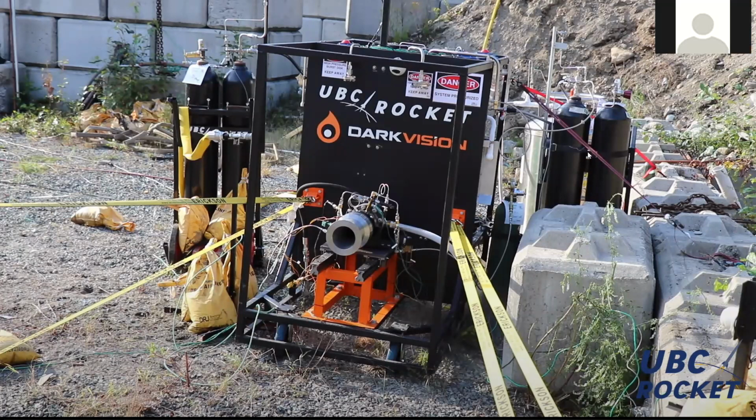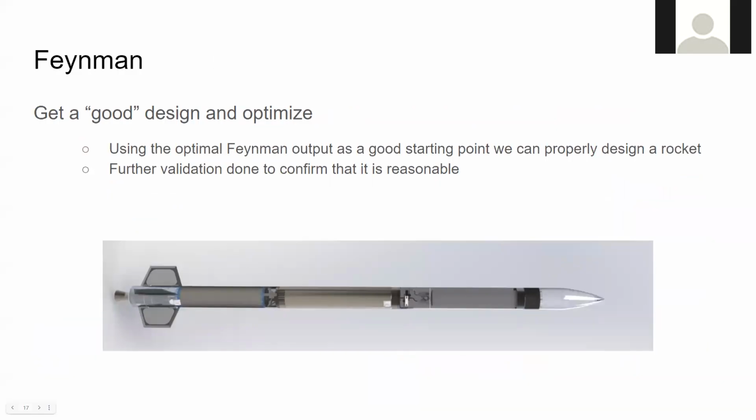Good question. Our nose cone is going to be carbon fiber, and then we're going to have an ablative coating on it. We want the carbon fiber because it has a very high stiffness to mass ratio, so it can sustain a lot of force, but it's not so great at high temperature.